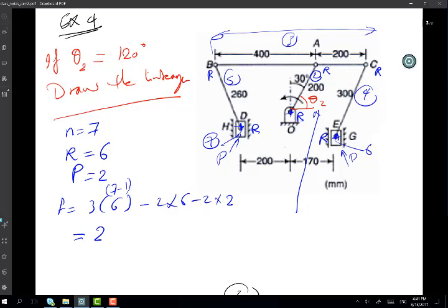So like in this case, you would possibly assume, if I want you to solve it, I'll give you the location of one of the sliders, because I would imagine one of the sliders will be driven by a linear actuator or something like that. If the center point had a rotary motor attached to it. So I didn't give you enough info over here for you to be able to draw the linkage. So that's why you couldn't draw it, right?